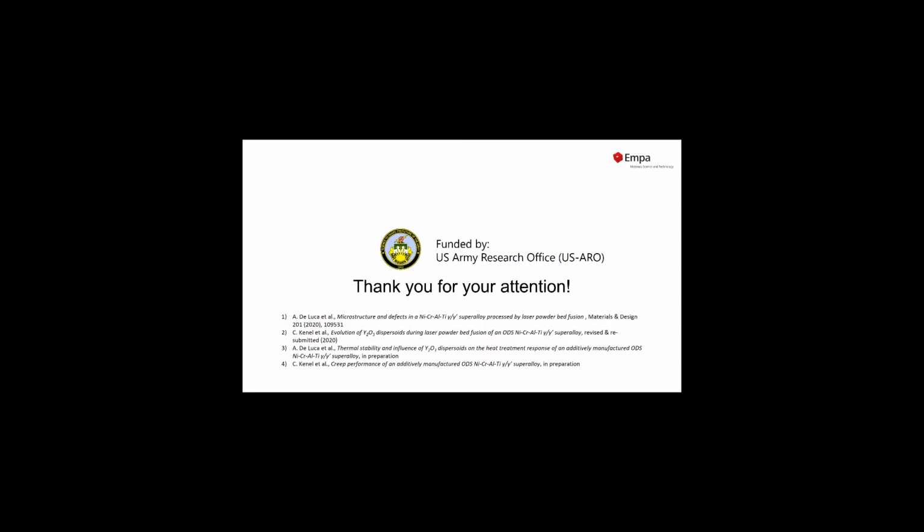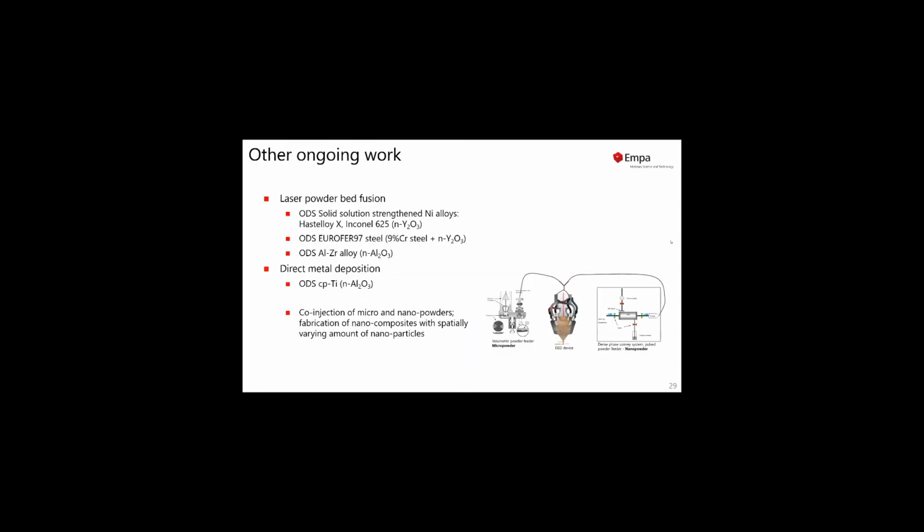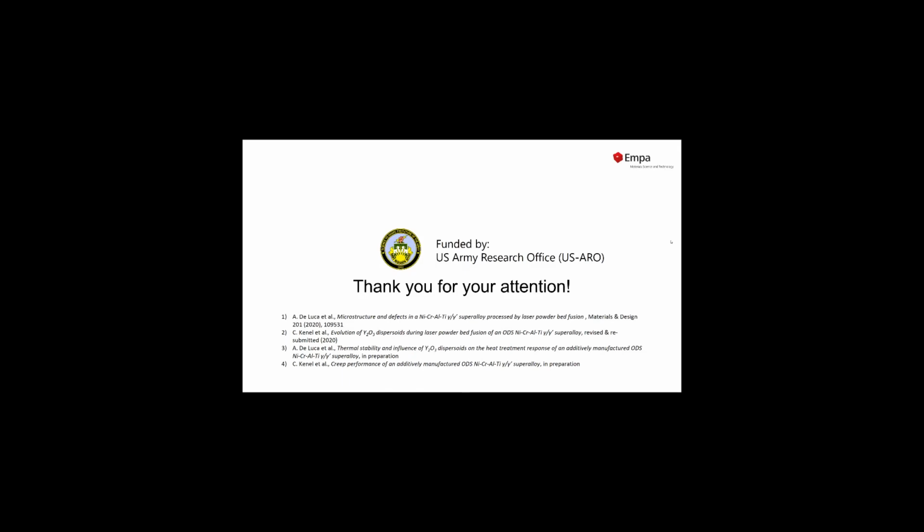Yeah, thank you very much, Christian. Very interesting talk. In steels, usually when I want to look at oxides, I go to the Ellingham diagram. That's the reference to know what kind of oxide would form in the material. But that's an equilibrium reference. So you look at what is the lowest Gibbs free energy and which oxide will result in the highest decrease. Now, that diagram does not have yttrium inside.